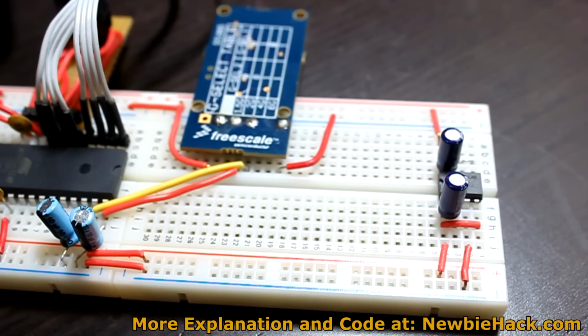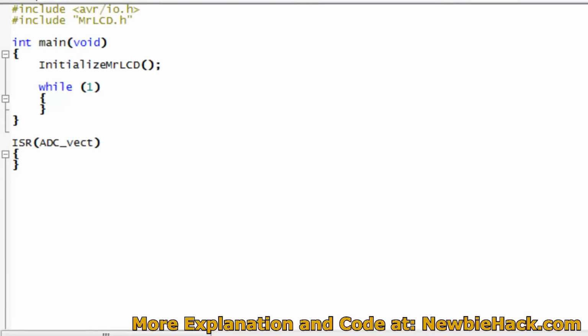So let's see what the program would look like if we're using two of these channels. Let's start with our skeleton code like we usually do. We have the standard io.h, we have the MrLCD.h library file, so we can use the LCD and display our numbers from the analog to digital converter. We have our never-ending loop, which we are not going to be putting any code inside, but we'll just use this to keep the microcontroller going.